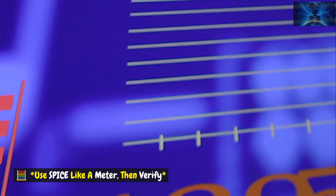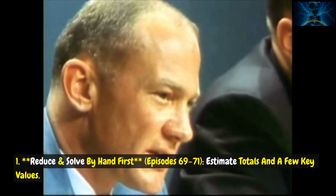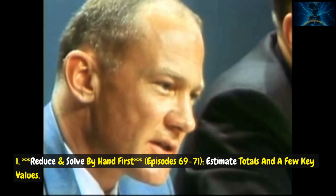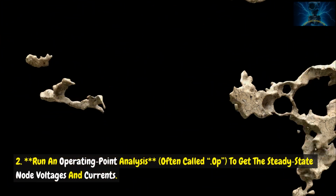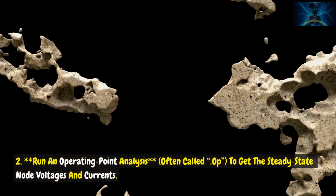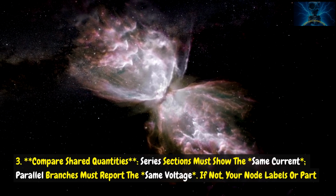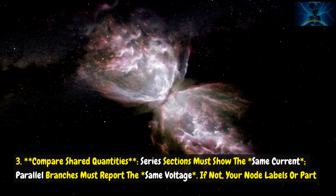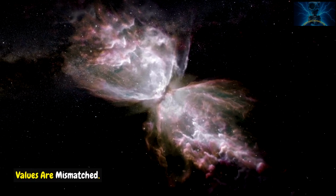Use SPICE like a meter, then verify. 1. Reduce and solve by hand first, episodes 69 to 71. Estimate totals and a few key values. 2. Run an operating point analysis, often called .OP, to get the steady-state node voltages and currents. 3. Compare shared quantities. Series sections must show the same current. Parallel branches must report the same voltage. If not, your node labels or part values are mismatched.